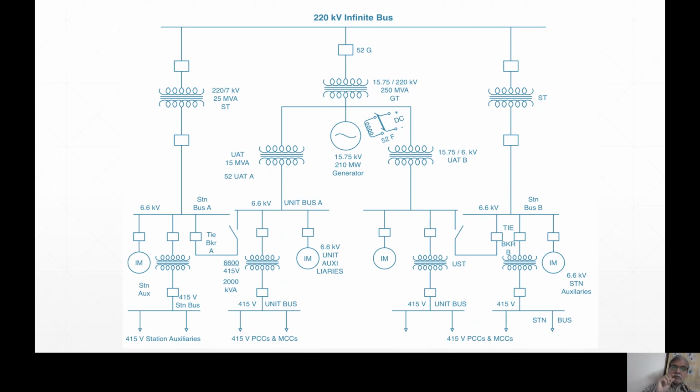That lubricating oil becomes hot, so that is taken out. It is cooled. Then once again it circulates. So for circulating the PF fan bearing oil, you have to use one motor, that is a 415 volt motor. For BFP also, that lubricating oil has to be circulated, and for that one, a 415 volt motor has to be run.